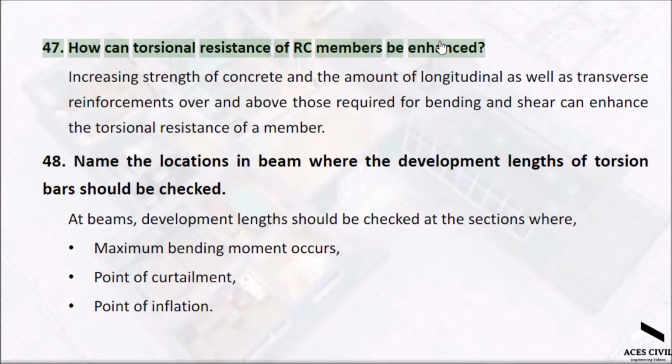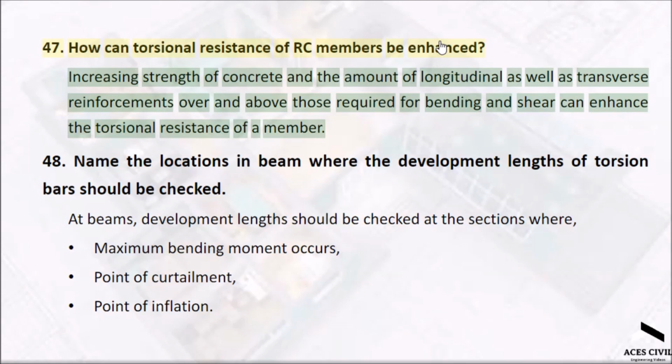How can torsional resistance of RC members be enhanced? Increasing the strength of concrete and the amount of longitudinal as well as transverse reinforcements over and above those required for bending and shear can enhance the torsional resistance of a member.